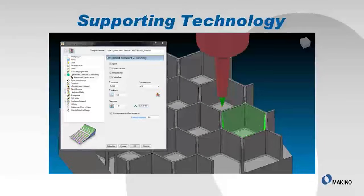In this particular scenario, we're taking a look at a CAM system with a standard 3-axis tool path. This one happens to be an optimized constant Z. What a lot of the CAM systems are doing now is combining the 5-axis technology with their standard 3-axis tool paths. This allows the programmers to use their standard 3-axis tool paths and then just add on the new tool axis capabilities to make sure that you're tipping away from the tool and avoiding collisions.